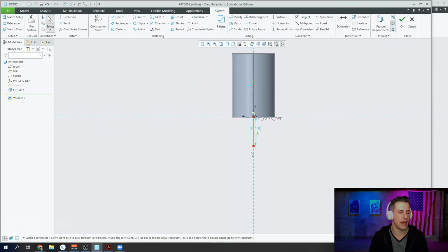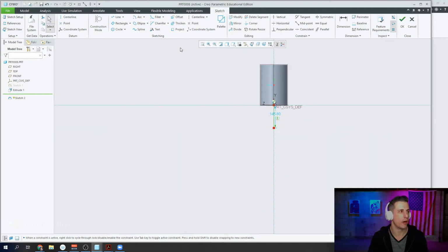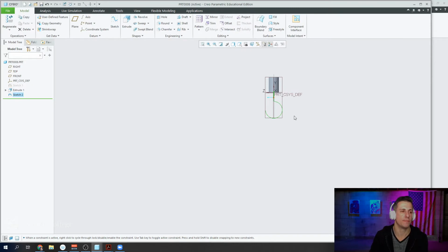And after that, make that a little bit longer, it's going to go into an arc. So I'm going to use the arc tool, and there are plenty of arc tools that you can get to in the drop down here. The one I'm going to use is center and ends. So I'm going to click first the center of the circle and then define the two ends by clicking here and then clicking there. So we have the hook shape.